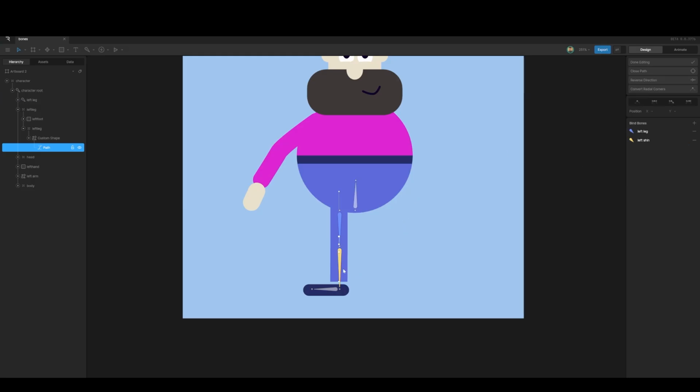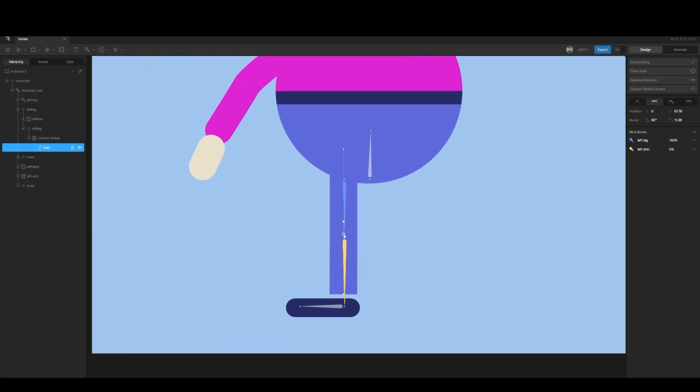And then if you see in the middle here, I've got another vertex here, and then there's two lines, because it's not a straight line. If it's a straight line, it would only be one, but it's two, and this line here gives it a bit of a bend, if it's got mirrored handles. So if I select all of these, now I just need to make it 50. So it's 50 influence on the one, 50 influence on the other one.